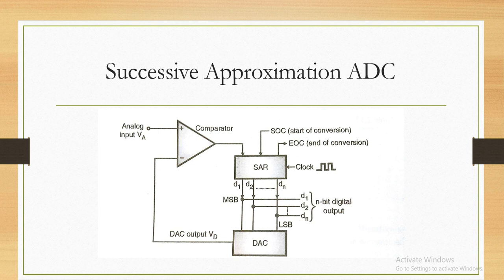In third year or in last year, you may use analog to digital converters. There is one very famous IC which is used in the system, that is IC ADC 0809. That IC is using this successive approximation type of ADC. You can search on internet IC ADC 0809.